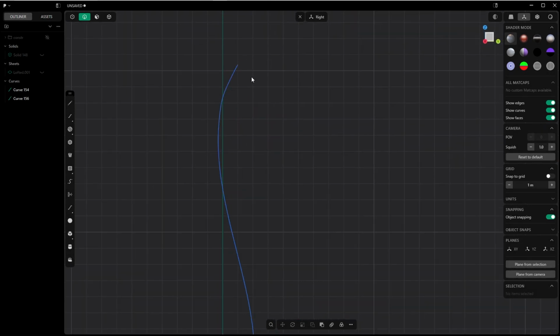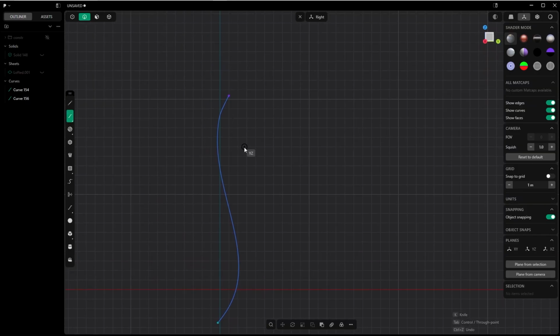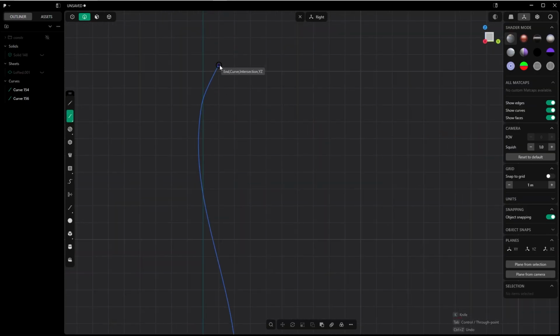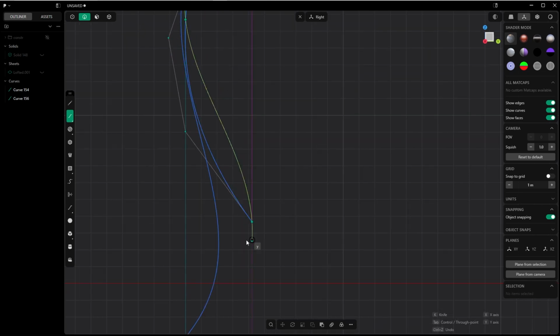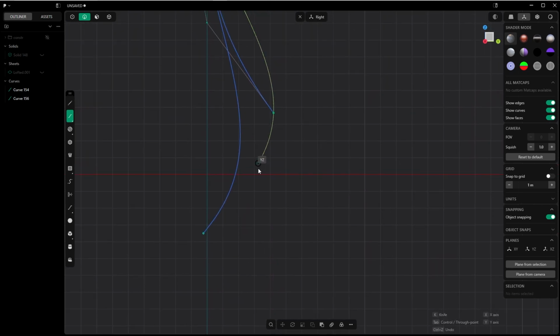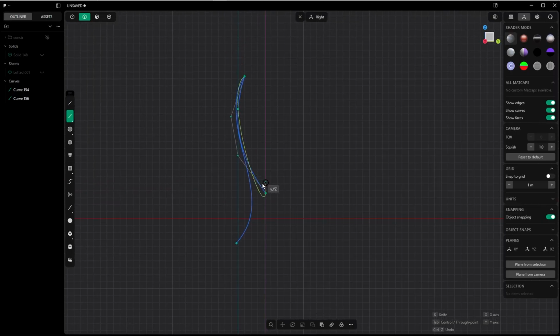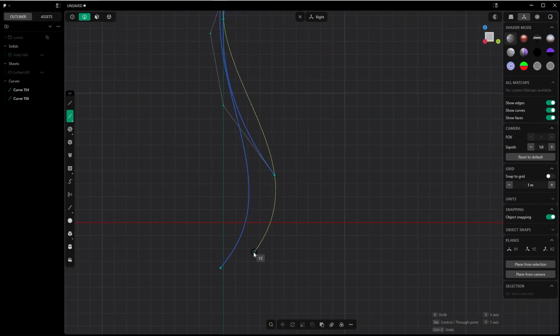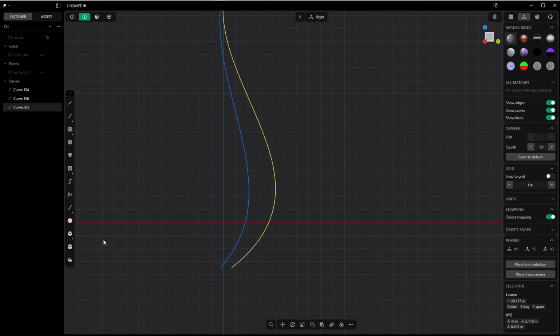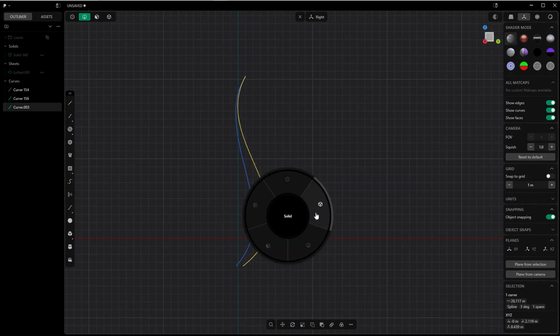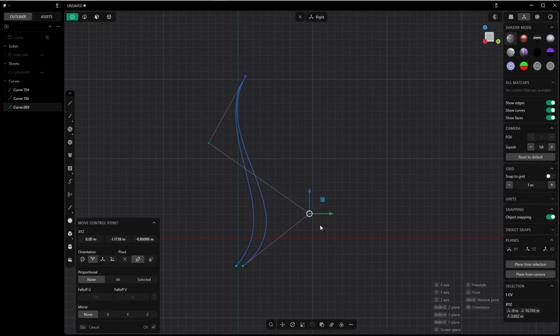Let's look from the right view, and again, create the spline curve. And this time I will start right away by snapping to this top point. And do something like this. Again, this spline curve should consist of 4 points. And the fourth one can again snap here at the bottom by pressing shift, creating a guide. So that's what we have, and we can do our fine tuning.